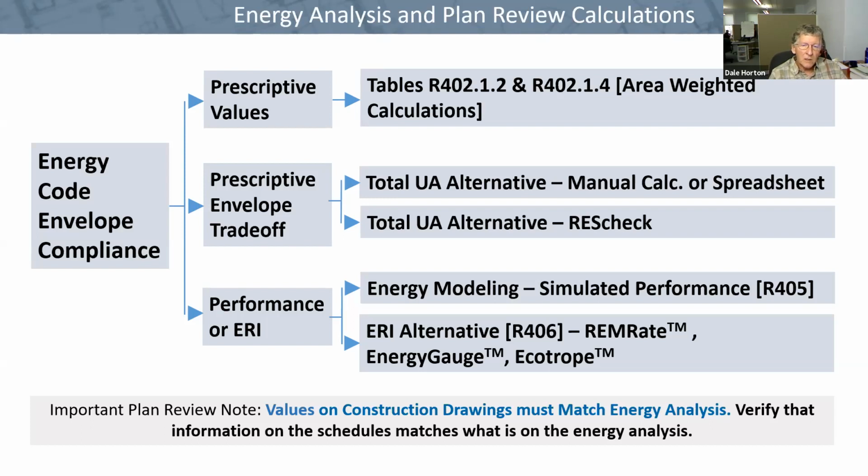As a code official, you would want to at least be able to understand that software so that you can do some sort of quick checks to make sure that what's entered in the software is actually in the construction documents. A few years ago, I did some work looking at different code departments and went through, randomly, REScheck submittal reports versus the actual plans, and found a number of areas where they disagreed. So even though you get a nice, neat report, as you do with REScheck or with the other software used for modeling in performance or ERI, it still behooves a code official to do some very general checking to make sure what has been entered into the software is actually what's on the documents.